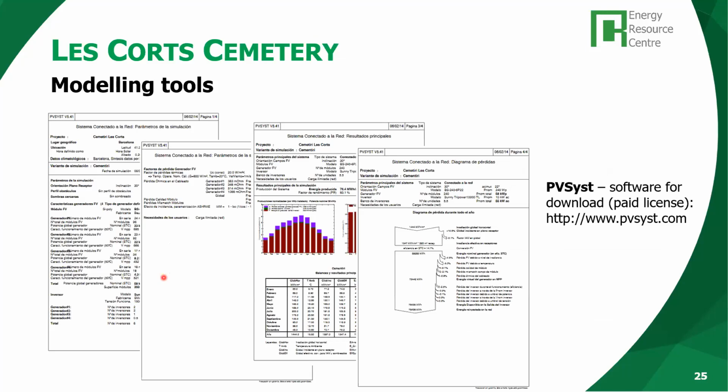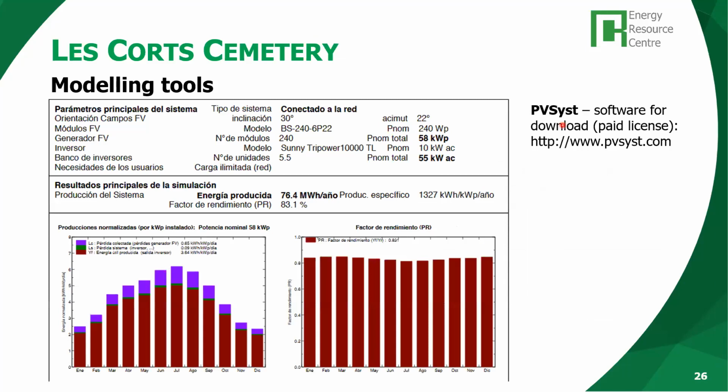Okay, so yeah, PVsyst was very helpful in providing different modeling and information, the losses that could be expected. It's also very useful for the connection of the strings. We need to be very careful with this, because we need to adapt the output voltage of the string to the input voltage of the inverter. If we go outside of this input voltage range, we can have problems with the production of the inverter. And PVsyst is very useful with this configuration.